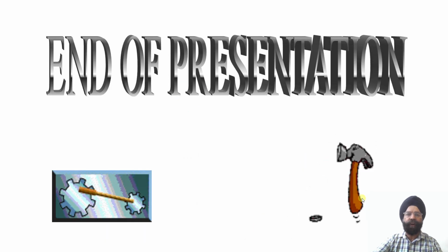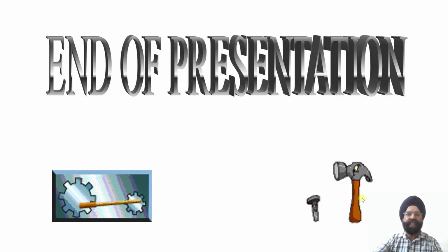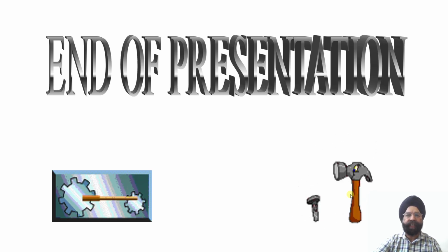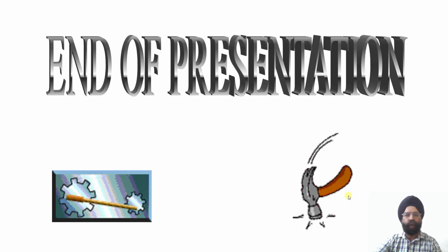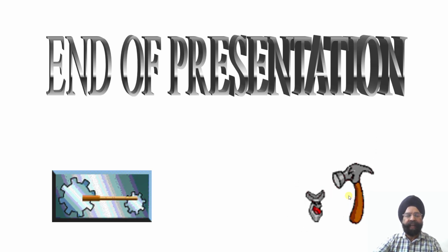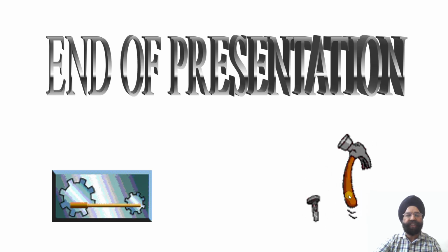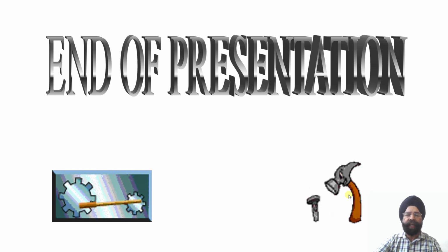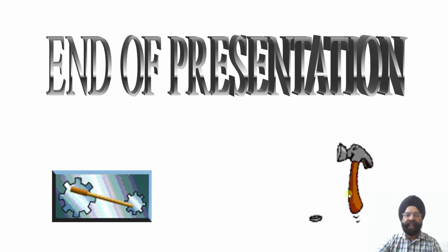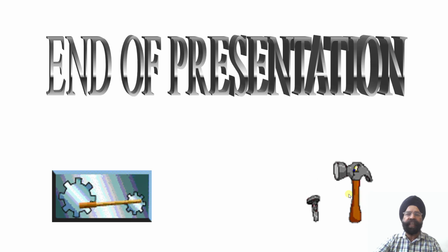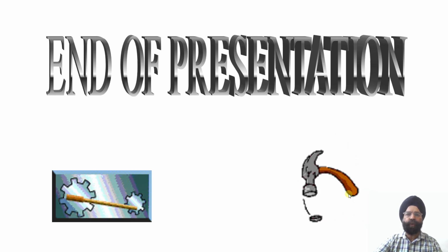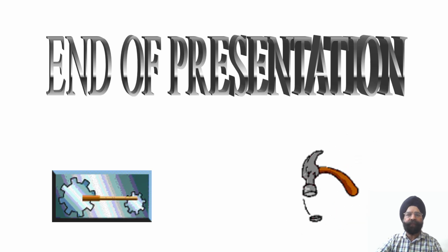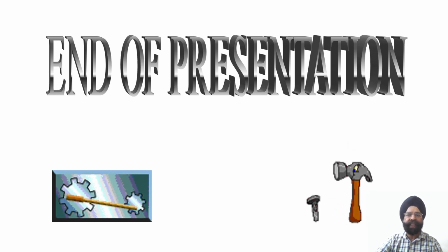So this is all for today. I hope that through this discussion you would have understood the mechanism of how we can convert the real life situation into orthographic projections to begin with, and after obtaining the orthographic projections, how we can use the rotation of the line method in order to evaluate the true length of a line as well as the true inclinations of the line with respect to the two reference planes, that is the horizontal plane and the vertical plane. We will be continuing with further discussion on a few more cases in the coming lectures.